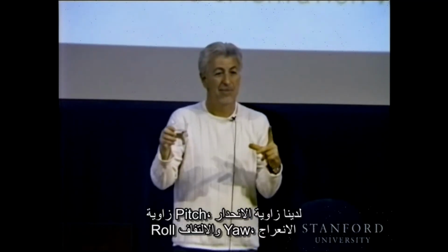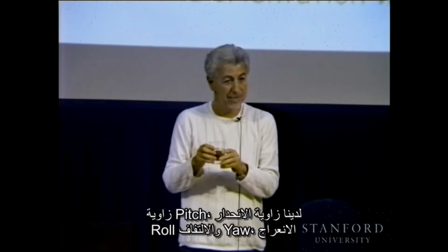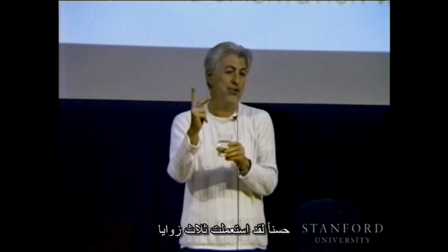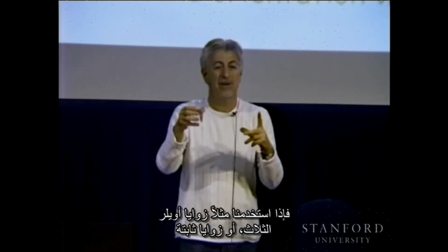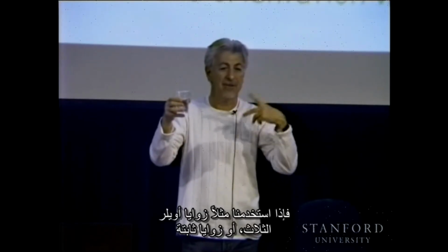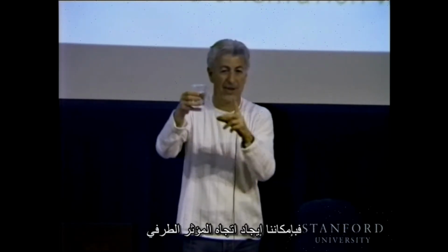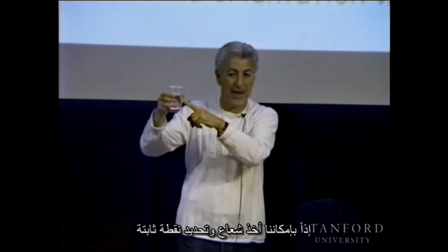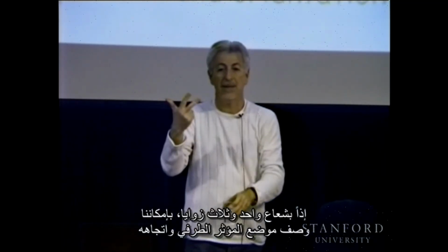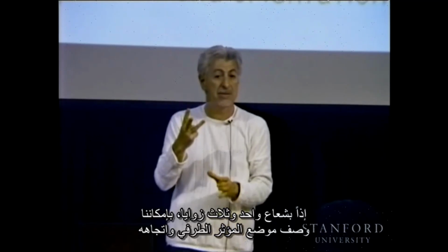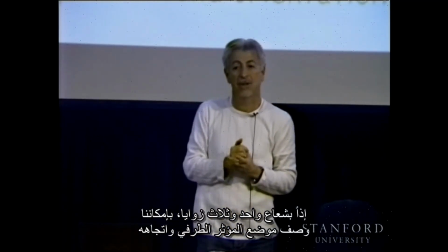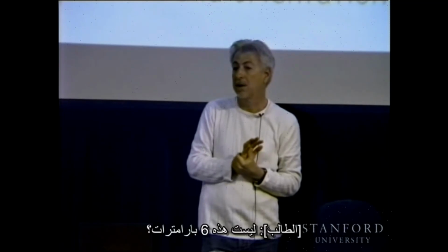Well, for the orientation, sometimes tilt, yaw and roll. Okay, you use 3 angles. So if we use like 3 Euler angles or fixed angles, we can find this position and orientation for the end effector. And for the position, X, Y, and Z. So we can take a vector and locate one fixed point. So with one vector and 3 angles, we can describe the position and orientation of the end effector. Yes? Isn't that 6 parameters? Perfect. 6 parameters.